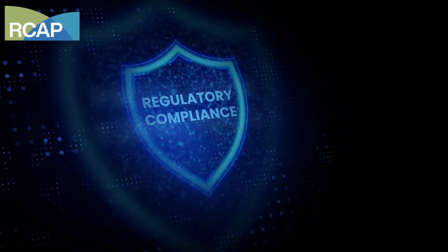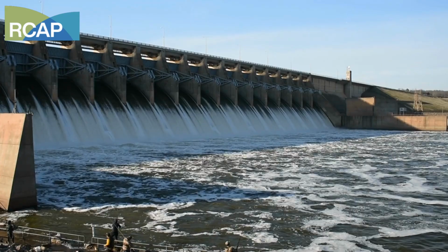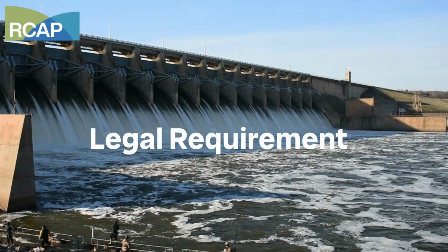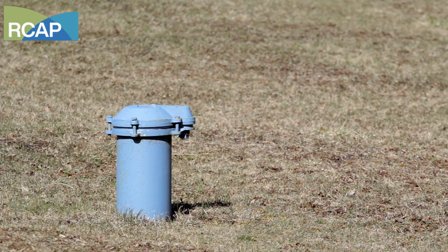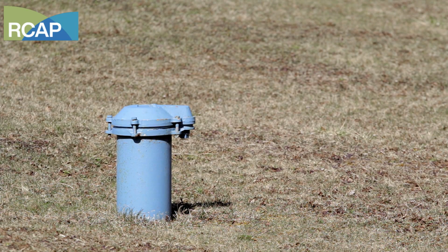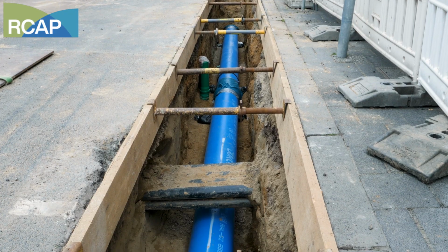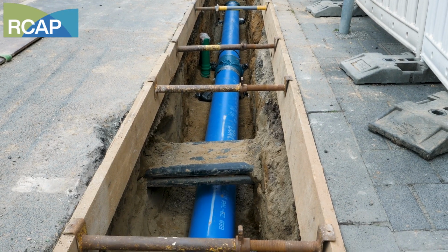There are some important regulations for disinfection. For instance, for systems that use surface water sources, disinfection is a legal requirement. Although most groundwater systems are not required to use disinfection, unless their source water has been deemed to be under the influence of surface water, most municipal systems will still choose to disinfect to add an extra layer of safety, especially for systems with older or larger distribution systems.